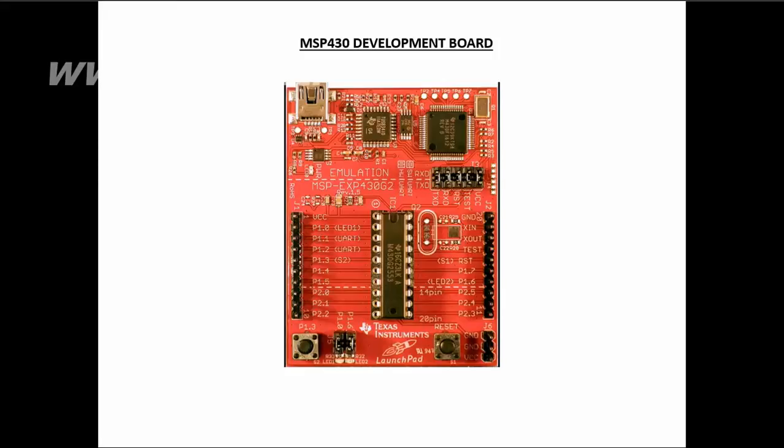This makes the MSP430 simpler than an 8-bit processor with 16-bit addresses. Such a processor must use its general purpose registers in pairs for addresses or provide separate wider registers. Here we are considering the MSP430 only in the 14 pin configuration.